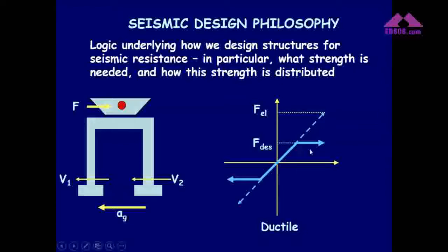And what we have to do to withstand this earthquake is put some ductile connections, details in our structure to resist this earthquake. The building will displace inelastically, but it will not collapse. The main purpose is this. Our building will get damaged after an earthquake, but it should not get totally collapsed.